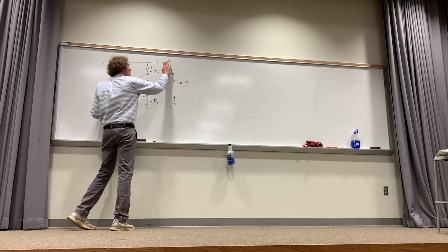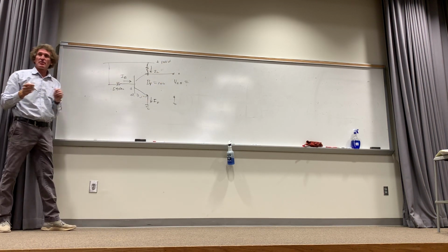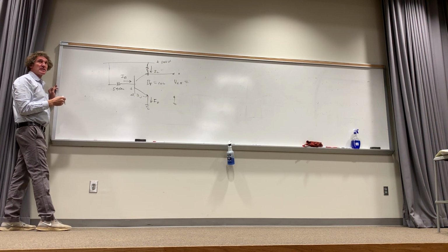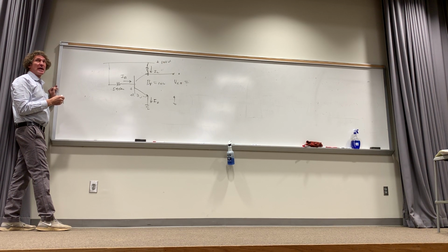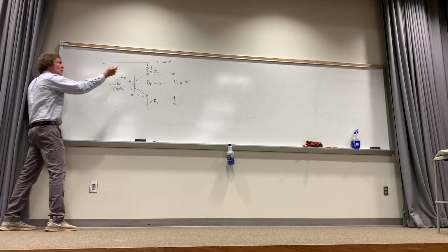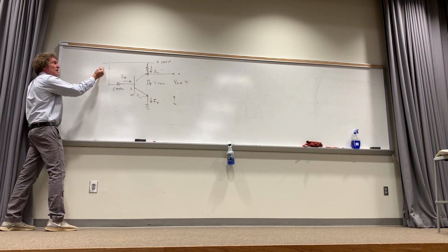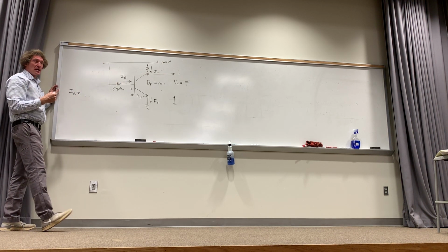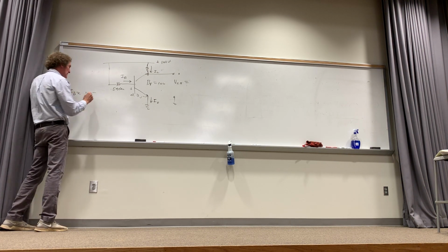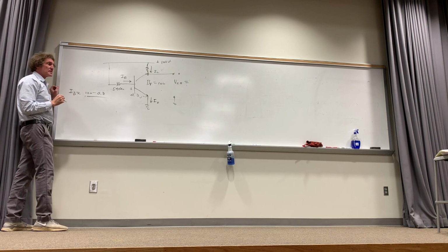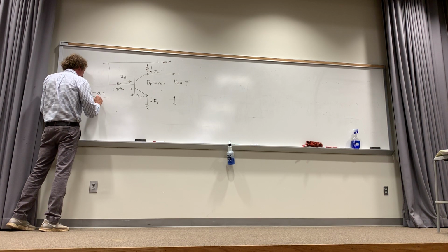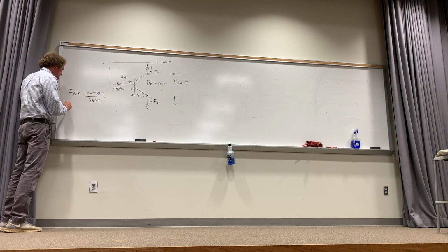All right, this is 100 volts, not 10, 100 volts. I want the collector and emitter voltage there. So, how do I do it? Where do I always go? Guys, what am I after first? Base current, IB. How do I get IB? I look for the voltage that's trying to drive current around the base circuit. It's the 100 volts, class. Do you see that? So I take 100. Then what do I subtract from it? 0.7 in this case. Almost no difference. What limits the current? The resistor, 540K. You'll notice there's no emitter resistance, right? So that gives me IB.